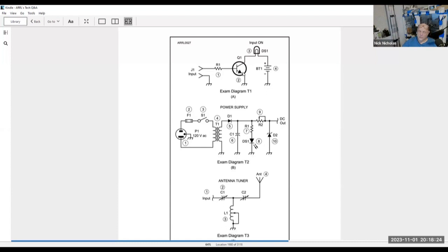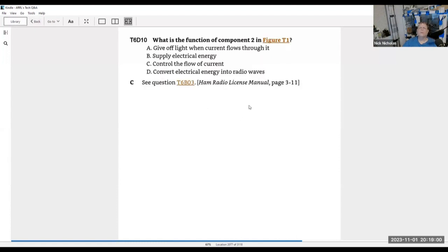So to make an NPN work, you've got to have a positive voltage to make that switch on. A PNP is the opposite way around. Does that make sense? Everything flows backwards from the NPN. They have advantages. There are times when you need one or the other. Okay, let's go back and look at the question.